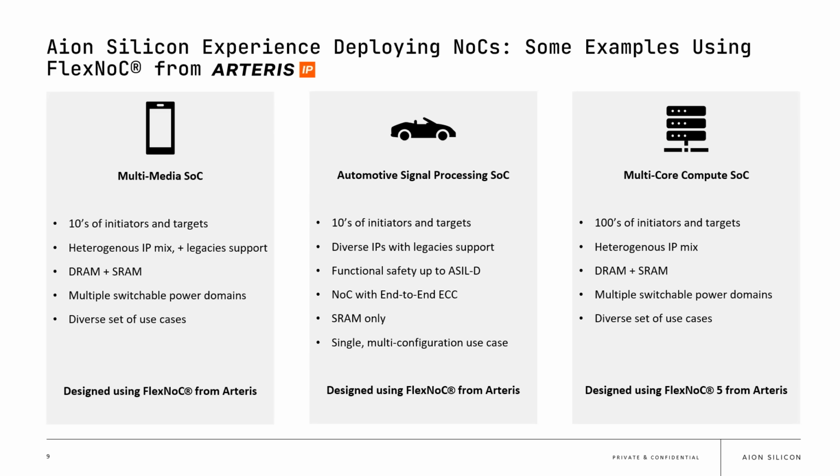The automotive SoC was functionally safe up to ASIL D, with the NoC supporting end-to-end ECC for that. We also have a multi-core compute SoC, which had hundreds of initiators and targets, a heterogeneous IP mix, multiple switchable power domains, and FlexNoC supporting all of these requirements. So just to give you an idea of the breadth of different SoCs that we've deployed with FlexNoC technology.